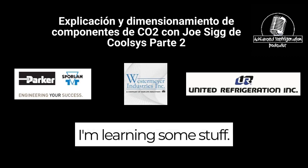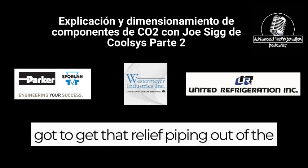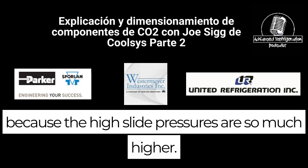I'm learning some stuff. Another important thing to worry about with a CO2 system, you got to get that relief piping out of the area where you're serving, where the rack is. This is way more critical than a DX system because the high side pressures are so much higher.